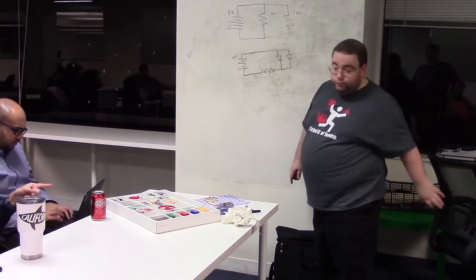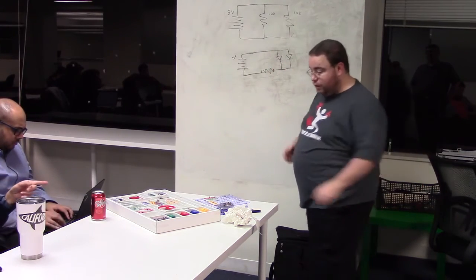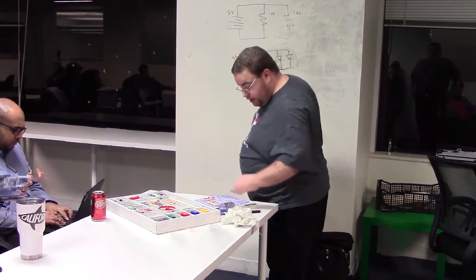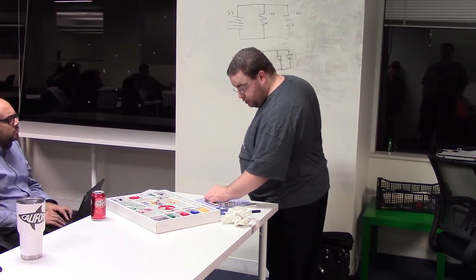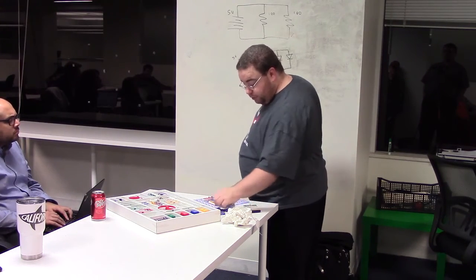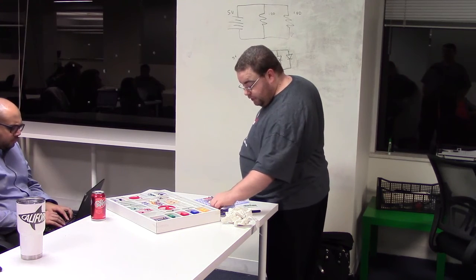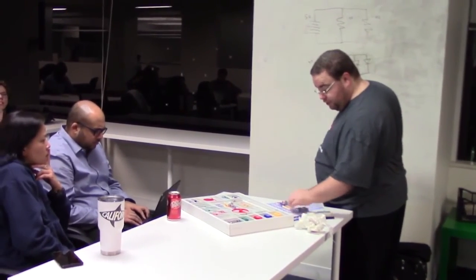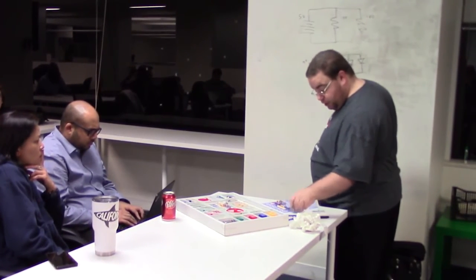So you can exchange one of those for a bulb, and everything should still work, right? Yes. Except the bulb probably not going to light up very much because we have the resistor in series with it. So the bulb needs a lot of current to operate. So if you have a resistor in series with the bulb, it's probably not going to work.